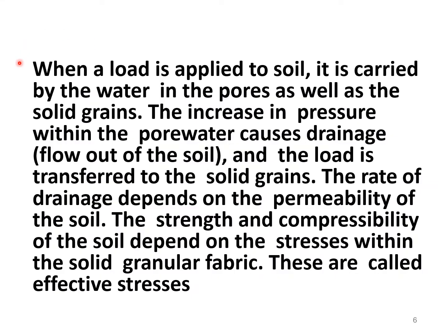This slide is very important. When a load is applied to soil, it is carried by the water in the pores as well as the solid grains. The increase in pressure within the pore water causes drainage, flow out of the soil, and the load is transferred to the solid grains.